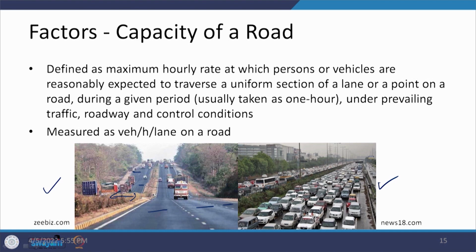So, directional traffic is safe in that form, and at the same time the amount of traffic, in terms of the number of vehicles which you can see passing this particular point as a reference line within a particular time frame, is what the volume is going to be, and accordingly we can find out the capacity for this particular system. But here it is working under lesser capacity, in terms of the volume being less than the capacity, and that is why you can find that all of these vehicles are moving at comfortable speeds, or it may be even the desired speed also.